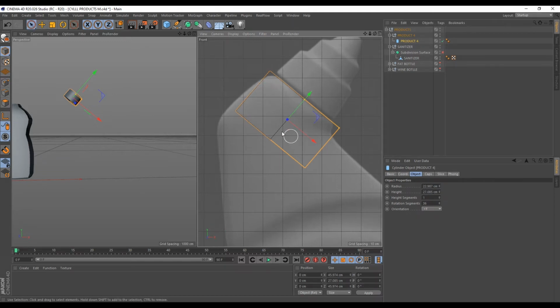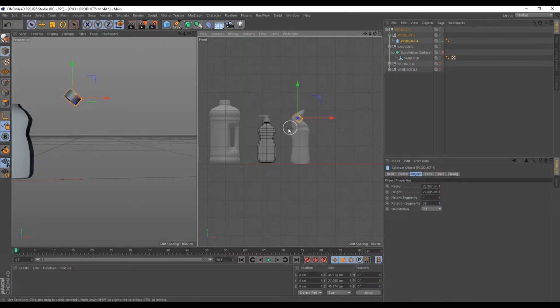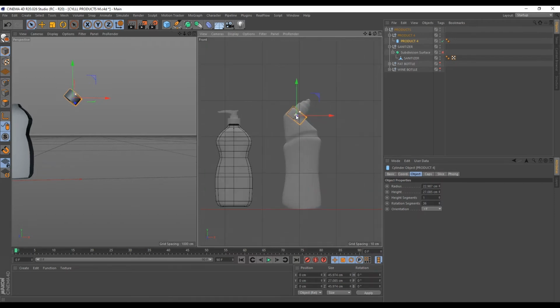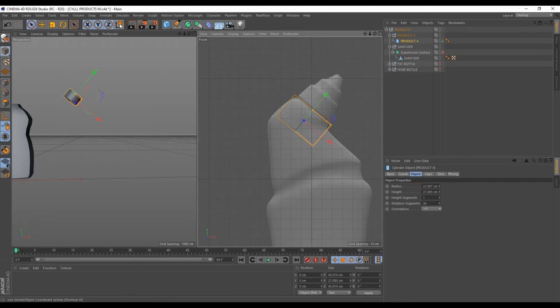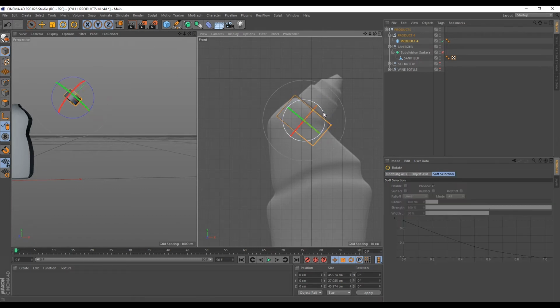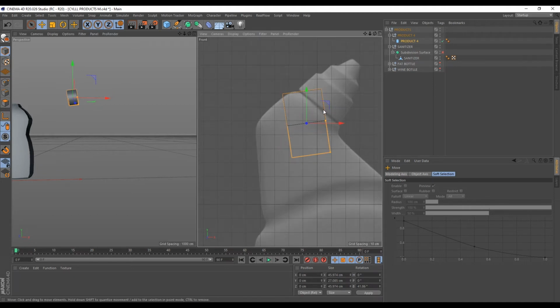So you see, as we rotated, our gizmo also followed this rotation. That is because this gizmo is on our local coordinate system. If you click on this, it will change it to our world coordinate system, and that will align with the default direction of our workspace, as you can see. But if you change this back to local, you can also hit W to switch in and out of that. If you change this back to local here, you see it follows the rotation of this object. So if we keep rotating this object, our gizmo will also follow the rotation. But if we change this back to world coordinate, it will revert to the default world coordinate system. This is going to be important when we're trying to extrude around this mesh. So I'll undo this to what I had before.